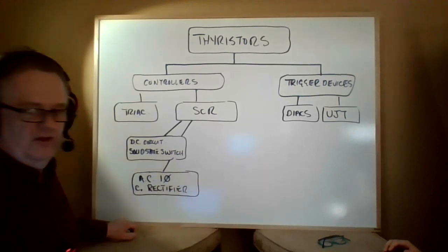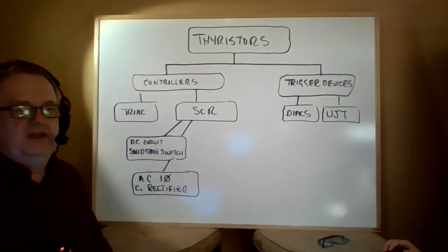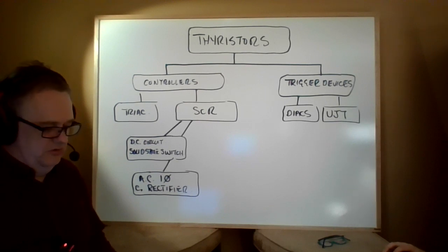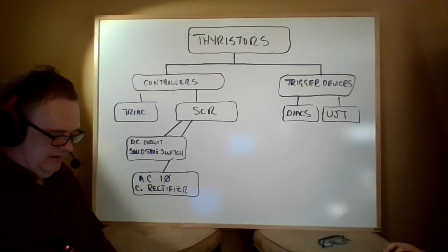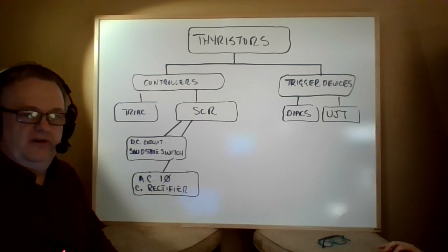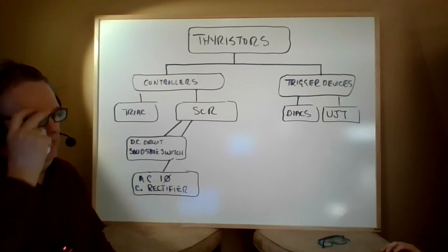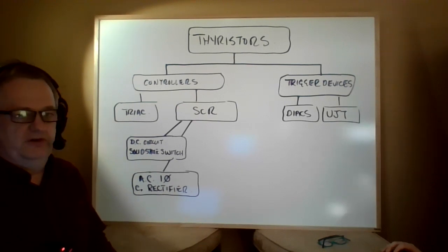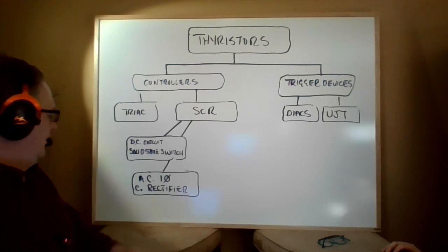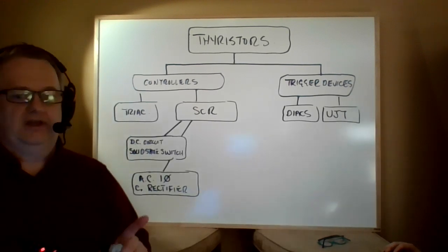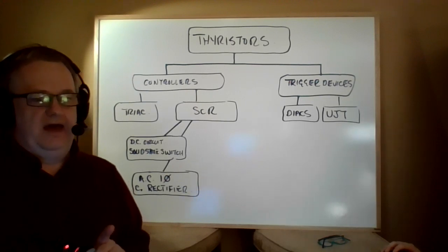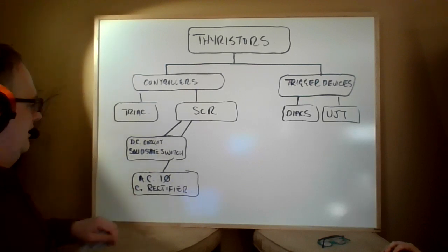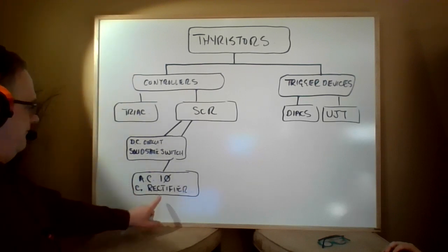So it's going to be like a single phase rectifier, but fully controllable from 0 to 180 degrees. So instead of a typical diode single phase rectifier, where we basically conduct for the total positive alternation of 180 degrees, now we're going to be looking at a situation where we can literally control when the SCR turns on, and literally how much load waveform we get.